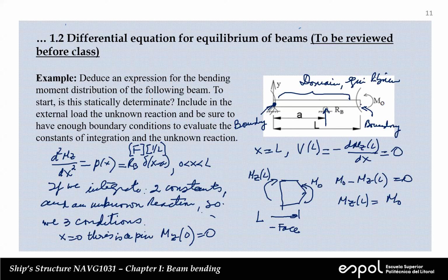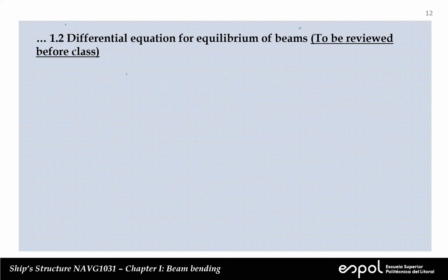Since the function that we try to determine is the bending moment, those boundary conditions have to be the values of the bending moment or the first derivative of the bending moment. Yeah, but the first derivative of the bending moment is the shear force. So in this case, we have a complete problem and we can proceed to integration. Let's do just one step of integration. Okay? So here,